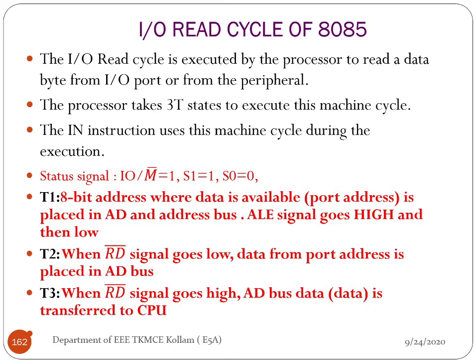But in the case of the AD bus, we need to make it free during the second and third clock cycles. For that, we can have a demultiplexing process by means of the ALE signal. The ALE signal goes high and suddenly goes low during the first clock cycle of every machine cycle. During the second and third clock cycles, the address data bus is free.